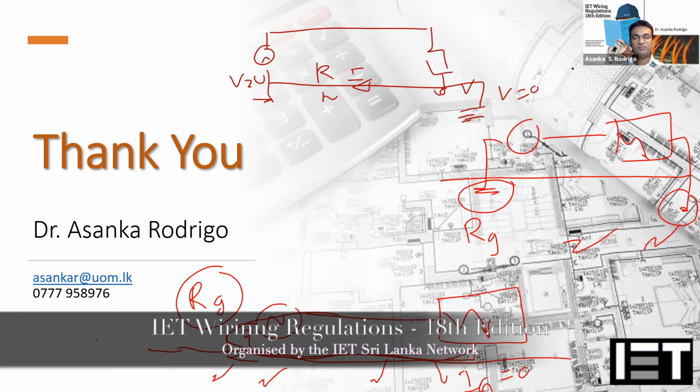Next question is, if we use a TN earthing system, it will generate high fault current in line to earth fault. Are RCDs still used for a TN earthing system? Yes, it doesn't matter, because if the fault current exceeds a certain value, the RCD will trip off and disconnect the circuit. But depending on your fault current, you have to decide.